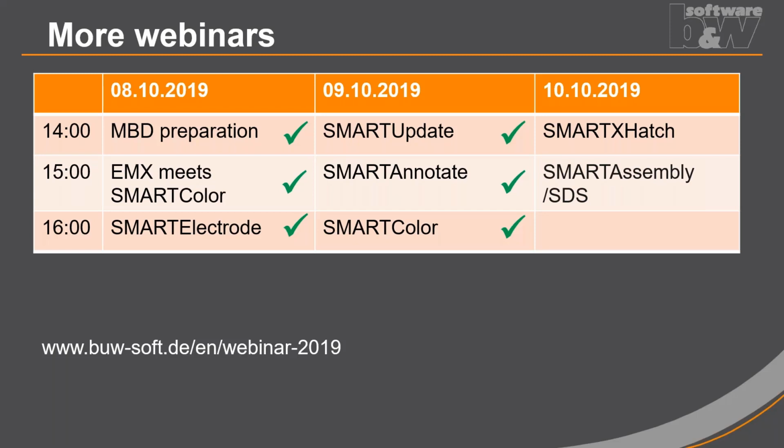And it's also possible to have variable text which is dynamically filled, so no need for hard-coded values inside the symbols. And also it's possible to activate a certain group within the symbol, so we're activating maybe an area which has a certain color. And there's a global configuration option which allows you to define a scale for the symbols. You can define the size of the symbol individually for each color code, and also globally within the configuration, like creating symbols with double the original size. So yes, it's definitely possible.